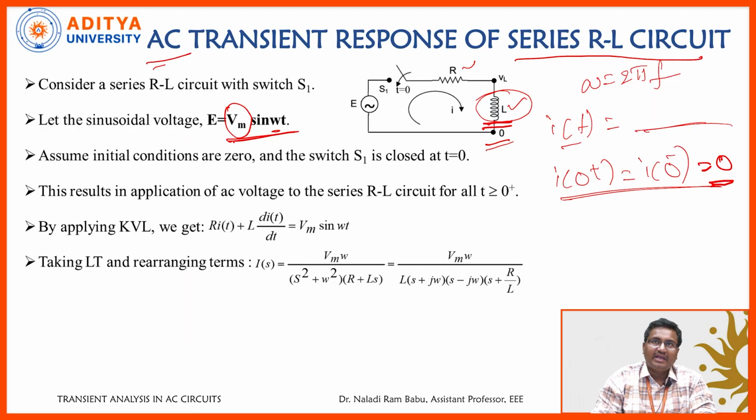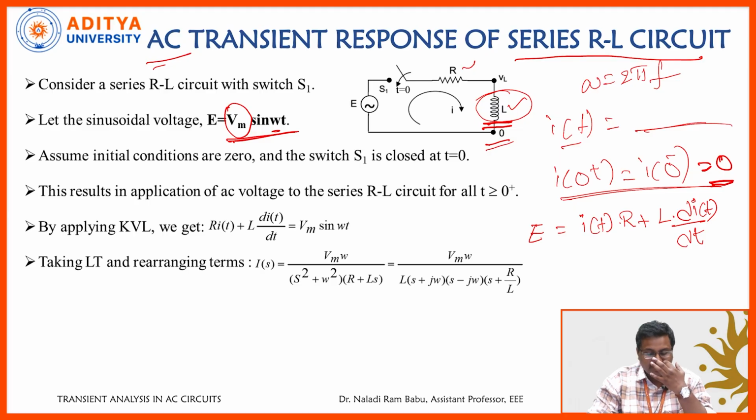Now I am applying KVL for this circuit. E is equal to I of t into R plus L into di by dt, where I of t is the series current flowing through the circuit, R is the resistance, L is the inductance, di of t by dt is the rate of change of current, and E is the supply voltage.